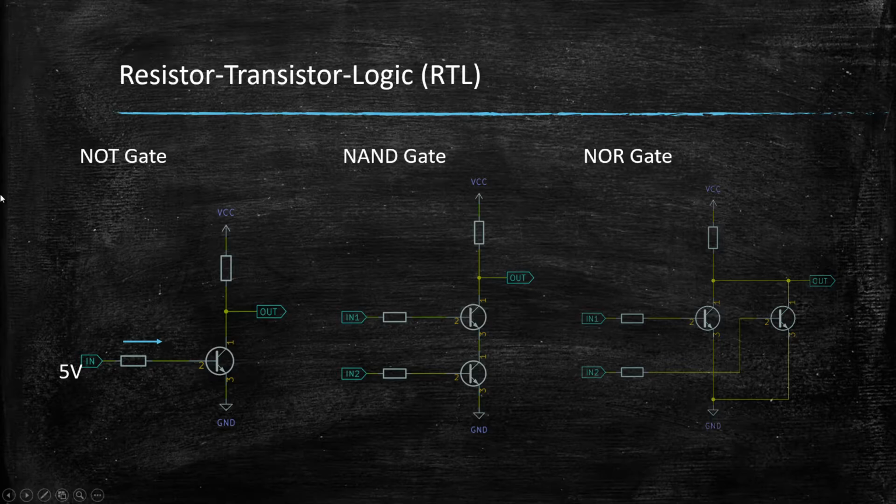And that also plays into how we size our circuits, because let's say our transistor has an amplification of, let's say, 100. We basically have to make sure that the current we put in is the current that is needed to get a full voltage drop over our load resistor here once our transistor is conducting, with a nice safety margin on top.